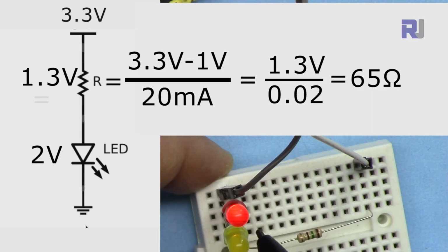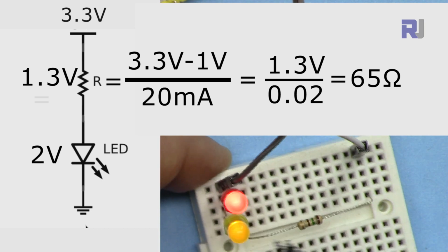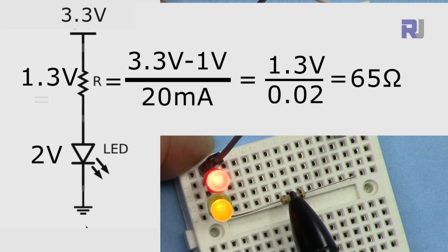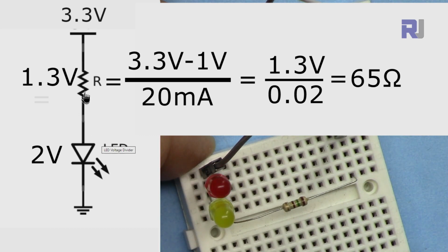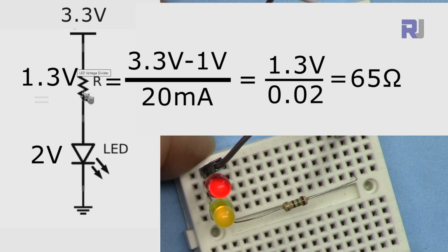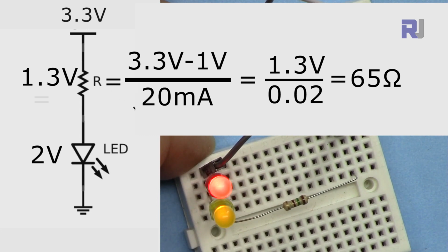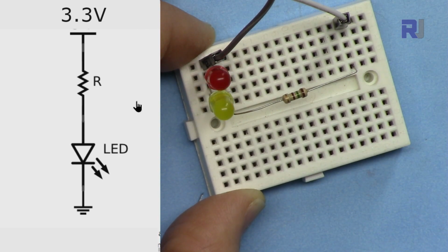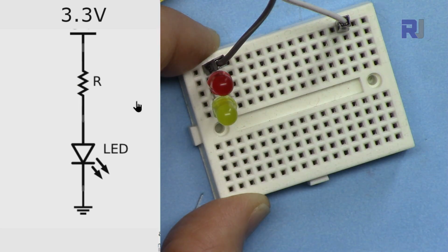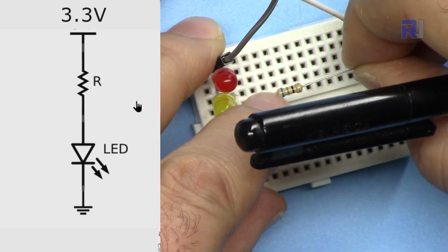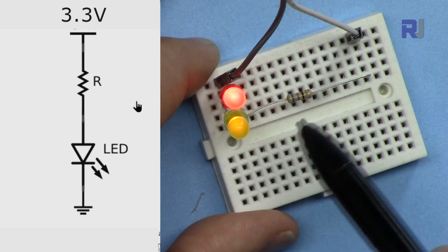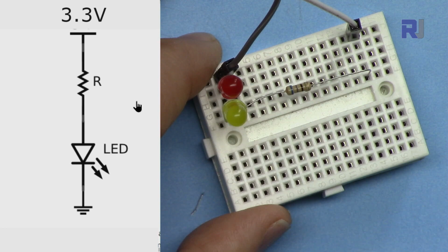Now, when you connect two LEDs together, the amount of current will be doubled, and the voltage drop will be higher here, so we have to reduce the resistance. Now this was 10 milliampere, and now we have 20 milliampere passing. So here 1.3, again 1.3, because if you put two of these together side by side, it's still 1.3 volts. So R is equal to 1.3 divided by 20 milliampere. It will be 65 ohm. And here I'm going to put 68 ohms. And it will now be much brighter and properly biased, or voltage divided.